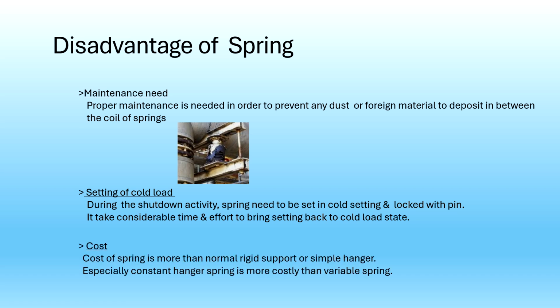Cost of spring is more than normal rigid supports or simple hangers, and especially the constant spring hanger is more costly than the variable spring hanger. So cost also plays a role when we go for the selection of springs.